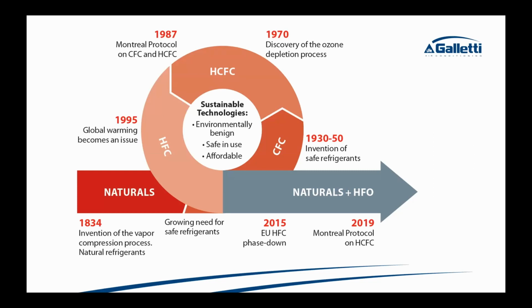a heat pump that produces hot water and cold water. It's a heat pump chiller, and if I use that product for heating only, it's fine. You can use it. But if I want to use that same product for cooling for that same building, then that refrigerant would be banned, which was pretty fascinating. So I went down the rabbit hole with Emily Lamb at the Mass DEP, and I see where they're coming from. There are reasonable substitutes for 410A as a chiller, but in terms of a cold climate, it's a great performing refrigerant. So now everybody's making the shift.